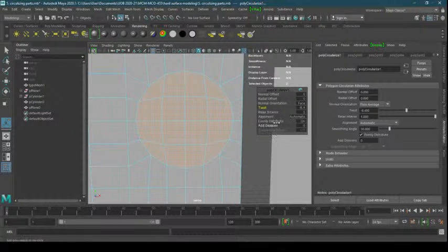I'll stop there. Now there is distribution, this is evenly distributed, so that means it will make a perfect circle. If I turn it off, it will not look nice, so I have to turn it on. Even distribution. Now there is the alignment option, and I am in automatic alignment. There is surface per vertex, then there is surface average.